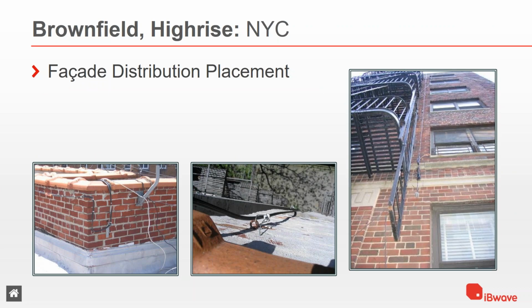In New York City, the major carrier addresses these pathway concerns in the older building by utilizing a facade technique to install cabling on the exterior of the building, whether you're leveraging a riser space interior to run a feed cable up to the roof and placing a splitter cabinet on the roof, or having a splitter cabinet mounted on the exterior of the building on the floor level and routing your riser cable up along the exterior, making penetrations either directly into each unit or into a hallway where you would route down the hallway to serve the units.